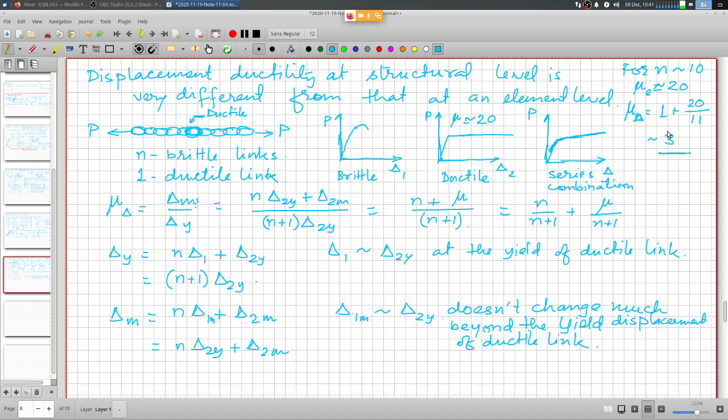So if I look at this problem in a reverse way, if I am to work with an assemblage, and I know that I can have ductility in only a few locations, in only a few elements, then I need to make sure that I generate sufficiently high ductility in those designated elements and locations in order to get a reasonable amount of ductility for the entire assembly, right?